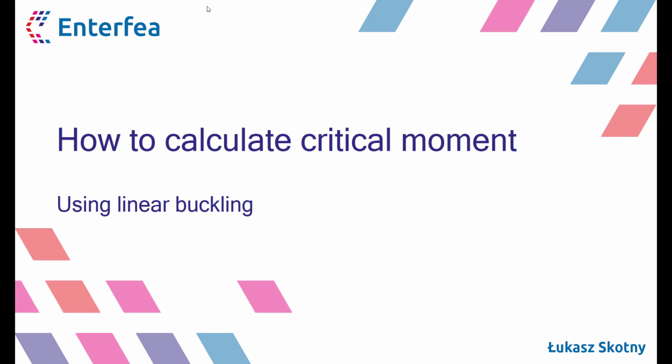Today I will tell you how to calculate critical bending moment using linear buckling analysis, sometimes called stability or linear bifurcation analysis. This is a really useful trick. If you are involved in structural design of any sort, you already know that most, if not all, codes require you to calculate this value when you want to design a beam due to bending. Critical bending moment is used to calculate slenderness, which is crucial when you design a beam for lateral torsion buckling.